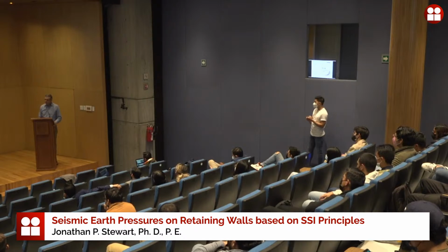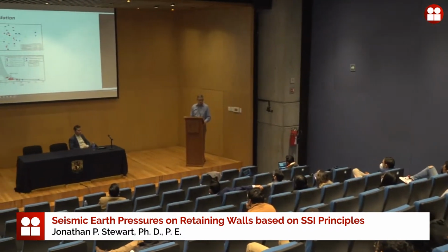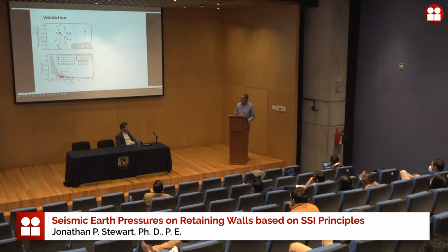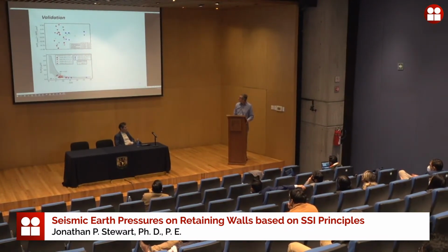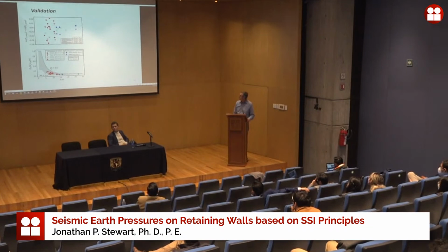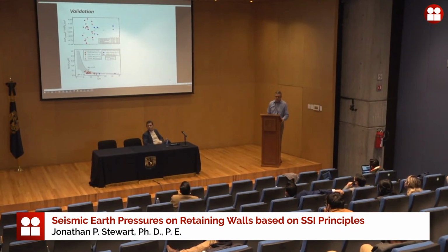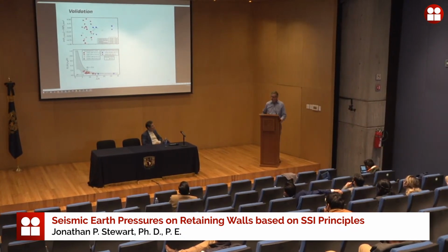The question you actually asked was, why is it that the red symbols, if you average them, are less than 0? The same is actually true of the Berkeley Davis test, but not to the same degree. The reason these are negative is because of simplifying assumptions we made in formulating the method. One was the rigid base assumption. Another was the lack of consideration of the heterogeneity of the soil. A few things like that force our pressures up a bit from what they would otherwise be.